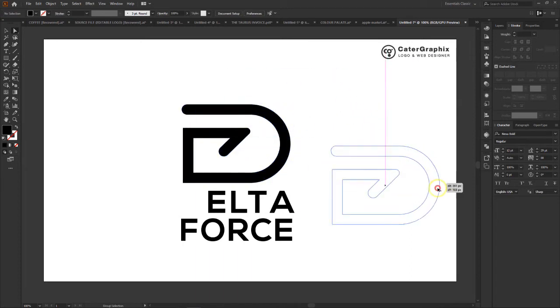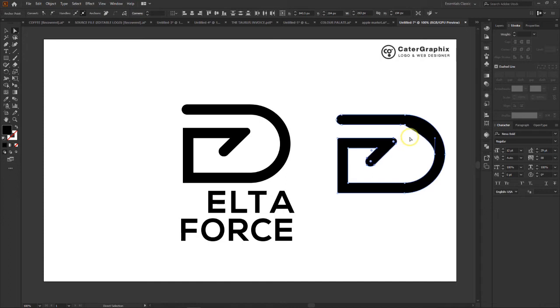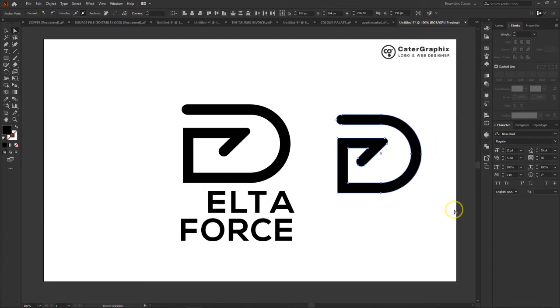So hold your Alt key and drag this thing out. So now we select everything at this part. You see, it touches this part. It will now start scattering the whole logo. Let me show you. You see what's going on? It will scatter the whole logo because that point is not rightly selected. So now we select only this part. Make sure it doesn't touch this angle. Select only this part, then you push it in a little. Then select this part to push it in to form a perfect D shape. So we have our D shape now.